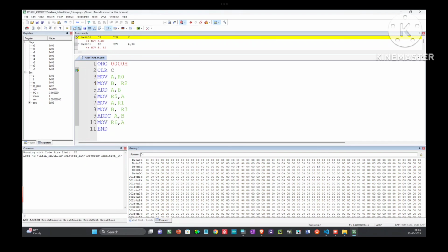In my case the start is 00, so I have to write D colon 00. This is for the RAM. If you want to see the content of your ROM, you can type C colon and the starting address and then enter, and it pops up.